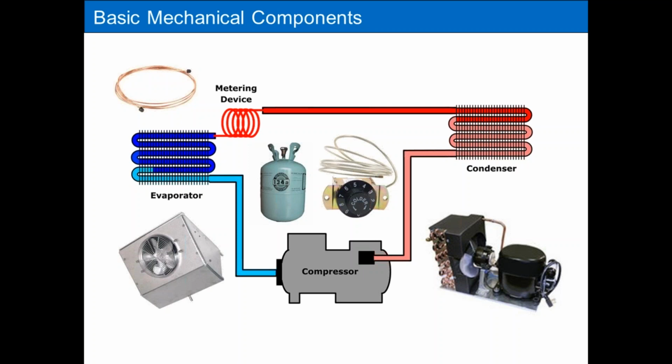The way these systems generally operate is the unit is controlled by monitoring the coil or evaporator temperature. It's cycled on and off by the temperature sensor being attached directly to the evaporator. And there's a relationship between evaporating temperature and case temperature. That's how these systems work. So keep that in mind. The type of temperature control that these systems use is coil sensing.